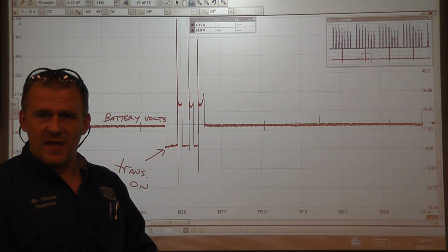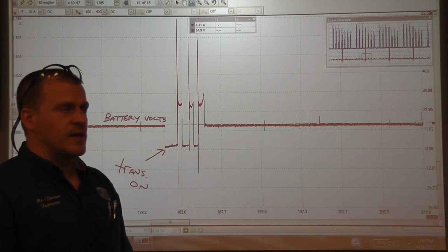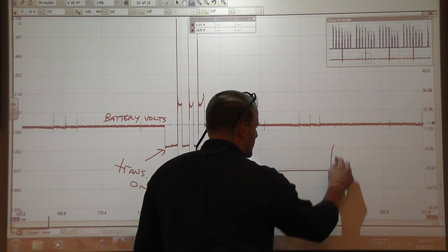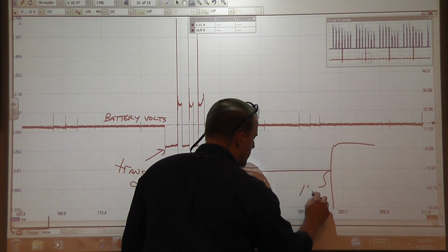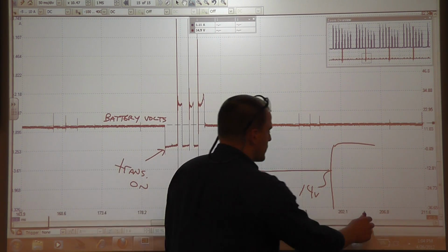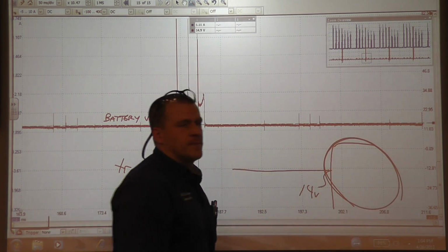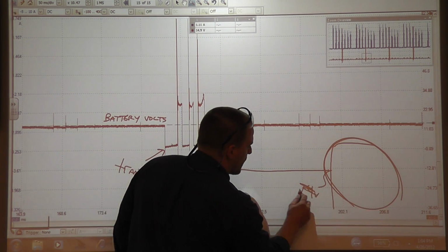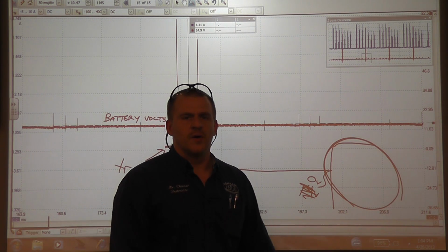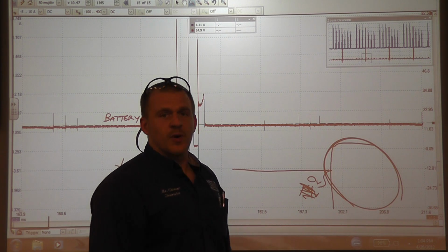But what we have on that number 6 wire is going to tell us whether or not we have an open in the circuit or whether we're going to focus at the computer. If we go to that number 6 control wire at the computer and we read 14 volts, where is our focus going to be on this truck? Our focus goes to the computer. If we read 0 volts on this control wire at the computer, where does our focus go? Harness, coil. It's an easy check. That's where we're going next.